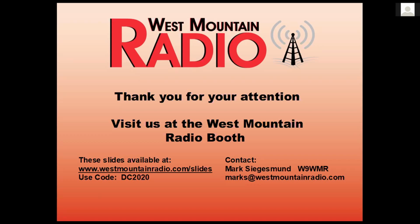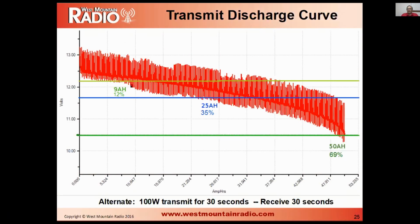If you remember one of the earlier charts, I showed you that if you're doing receive transmit on a car-sized battery, you're really only going to be able to use a third of the energy in that battery before the voltage hits that 11.7 volt limit that your radio wants. Yeah. So you're paying for a 74 amp hour battery or an 80 amp hour battery, but you're not getting that many amp hours out. You're getting a third of the amp hours out.